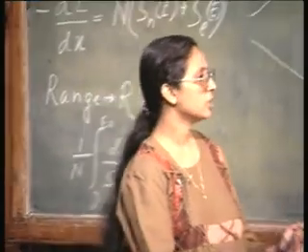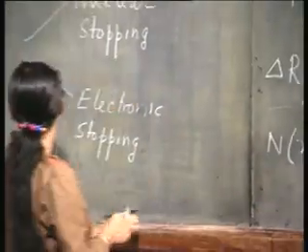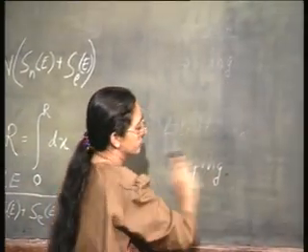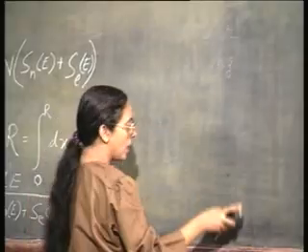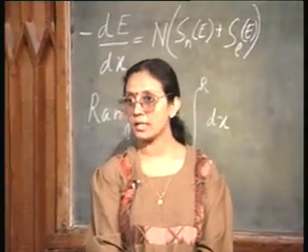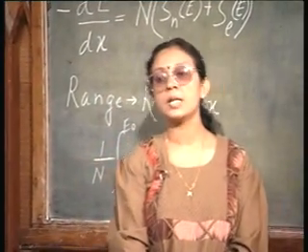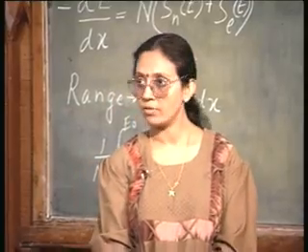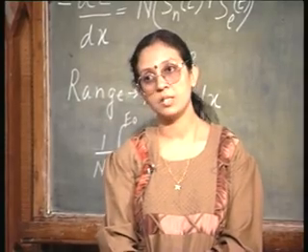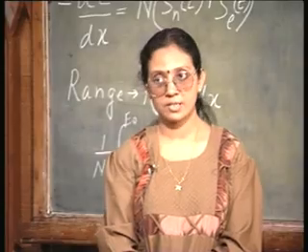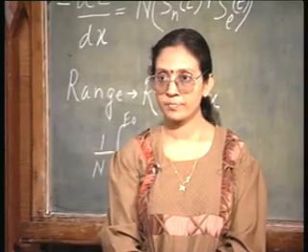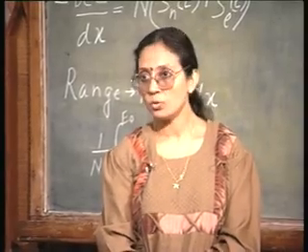If you want to calculate these things, you already know that the dose, or the total impurity put inside the semiconductor, is given simply by the area under the n versus x curve. Even in case of diffusion, you have seen that it is simply the area under the n versus x curve. In other words, I have to integrate n(x) from minus infinity to plus infinity.